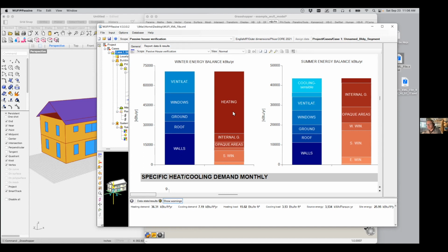So when it comes to our overall heating and cooling energy demand performance improvements, the game here is to shrink that heating portion, or on the right here, this cooling portion, to the smallest amount possible. So, okay, we have a whole bunch of losses, we have some gains, and then we have our heating energy. So how could we reduce the heating energy? Well, there's really only two ways. We could either hold the losses constant and increase the gains.